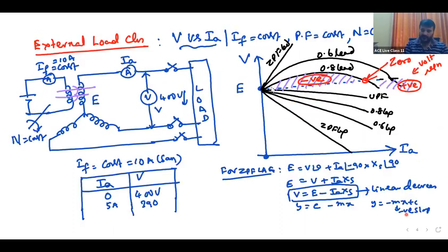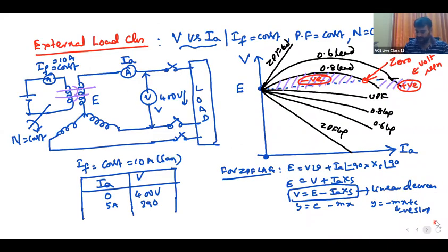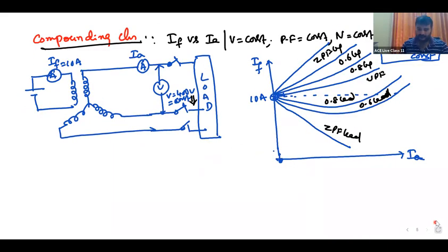They are just opposite. Here you see, voltage increases, so the field current decreases. As long as voltage increases, I will decrease the field current to maintain the same voltage, and when voltage decreases, we will increase. So just write reverse. Fine. So this is about the characteristics of alternators.